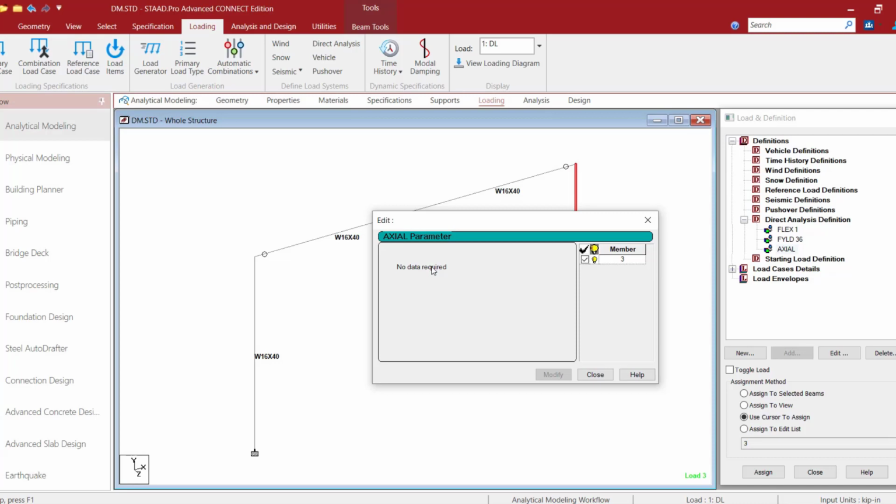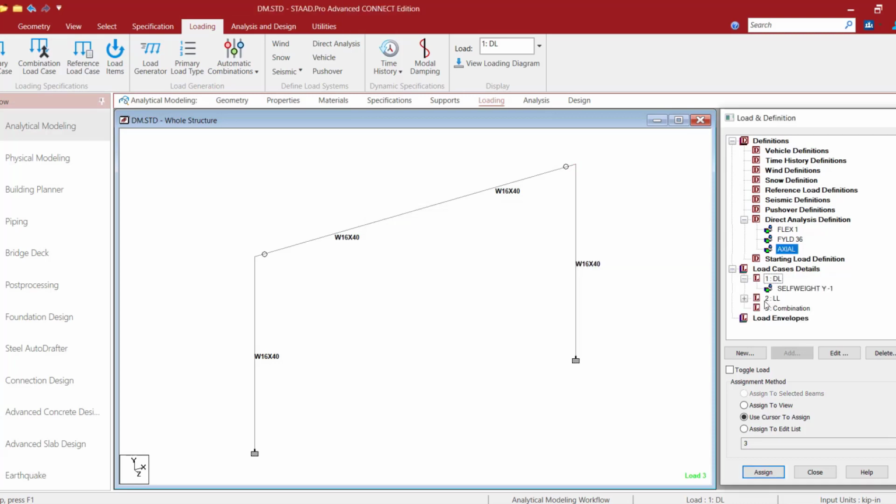Now our next step is to apply the loading arrangement in the model. First, you need to define the gravity load cases and all the lateral load cases if there are any in the model. So I'm taking only the gravity load case here. Now, as per the AISC code, the notional load of 0.002 of the gravity load case of that level must be included in the combination case.